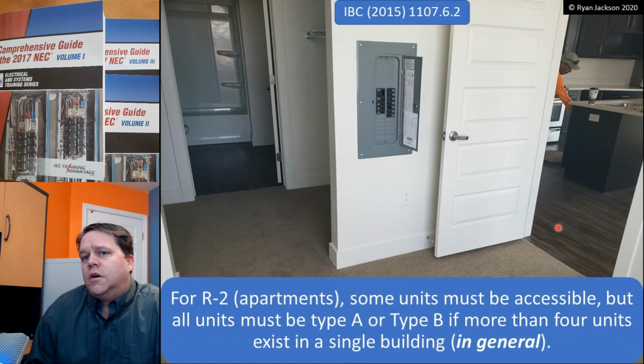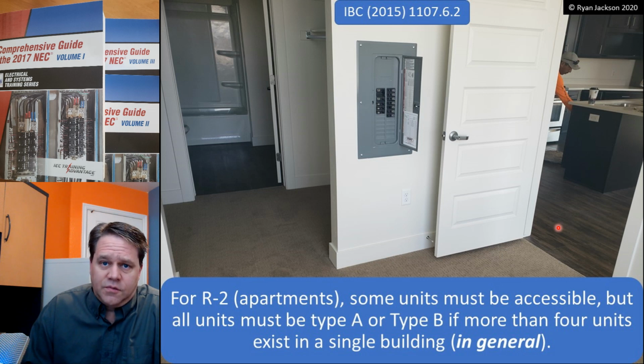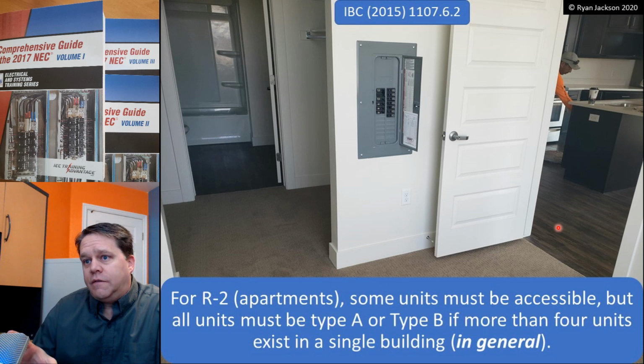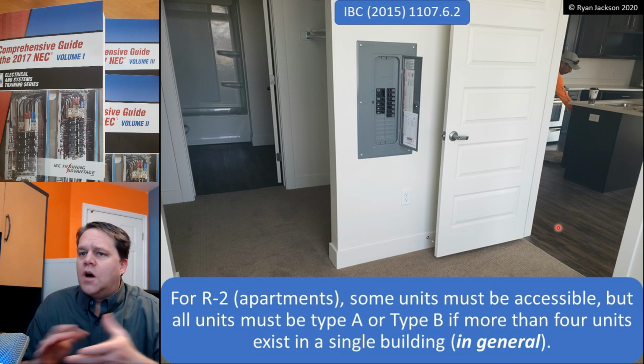Where it gets a little bit trickier is R2, which is apartments, not hotels and motels. For R2, some units must be accessible, but all units must be either type A or type B if more than 4 units exist in a single building. Now, I'm not going to get into type A and type B too specifically, but let me just say that there's essentially 2 concepts here.